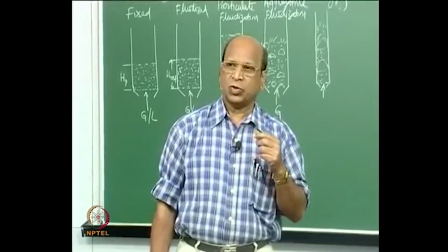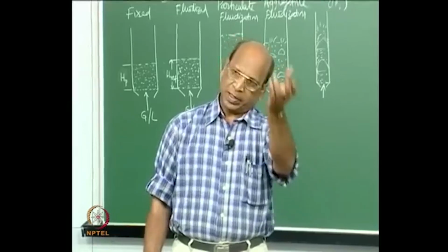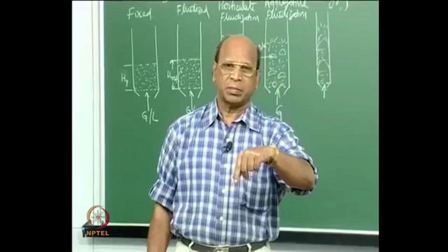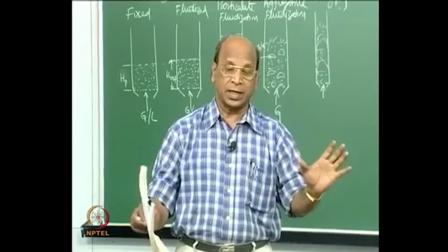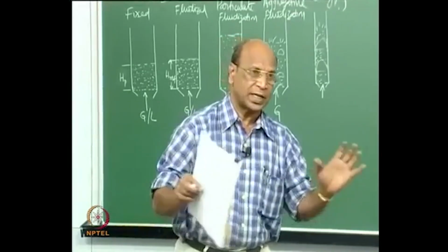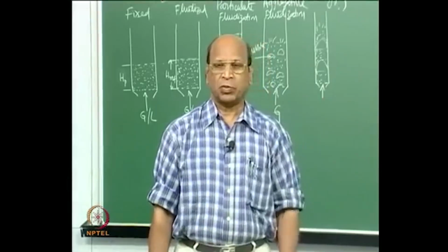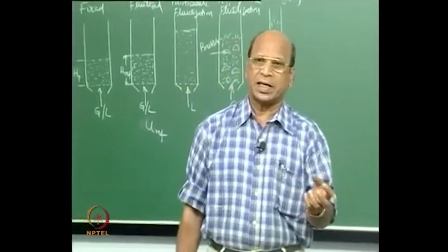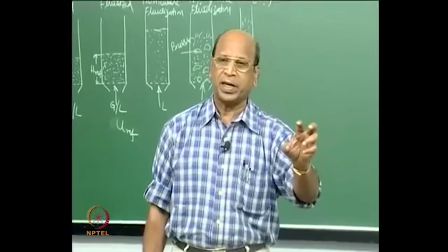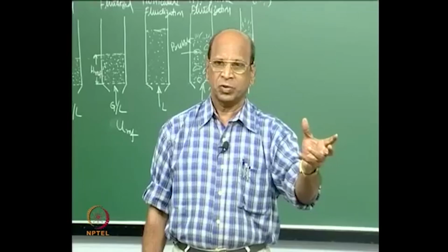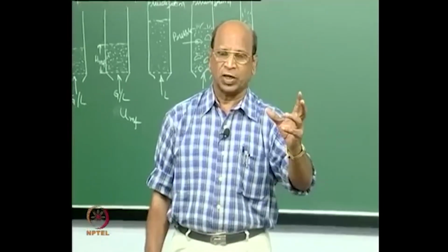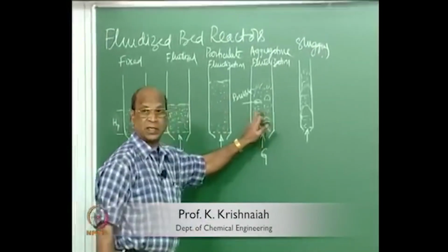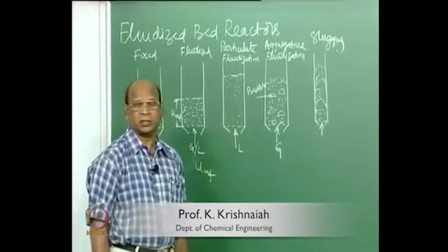Yeah. So, you allow the entrainment and then bring the solids again continuously and circulate them. What is the advantage? Because now I do not have bubbles, I can clearly find out what is happening at least in the bed. But what is the drawback? Drawback may be that the amount of solids in the bed may be small. So, normally it happens around 15% solids, 20% solids, whereas here I have 50% solids and also 60% solids.